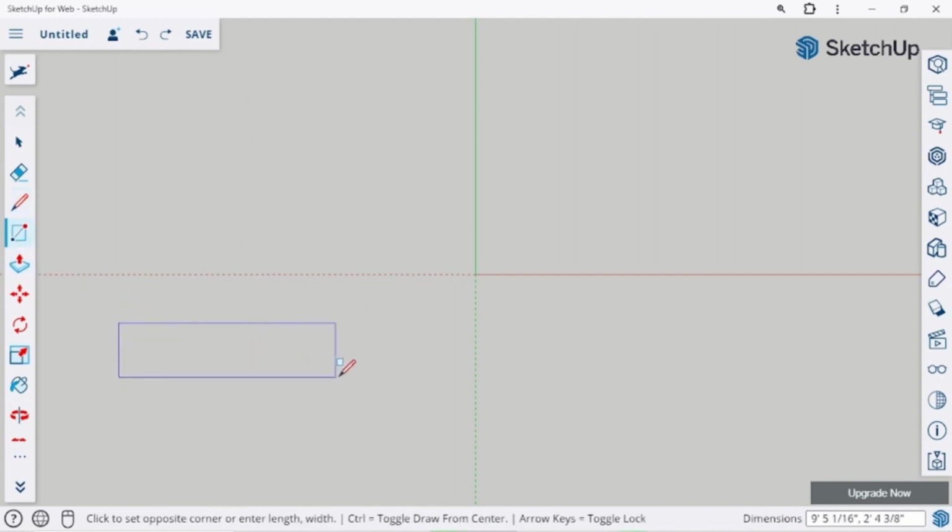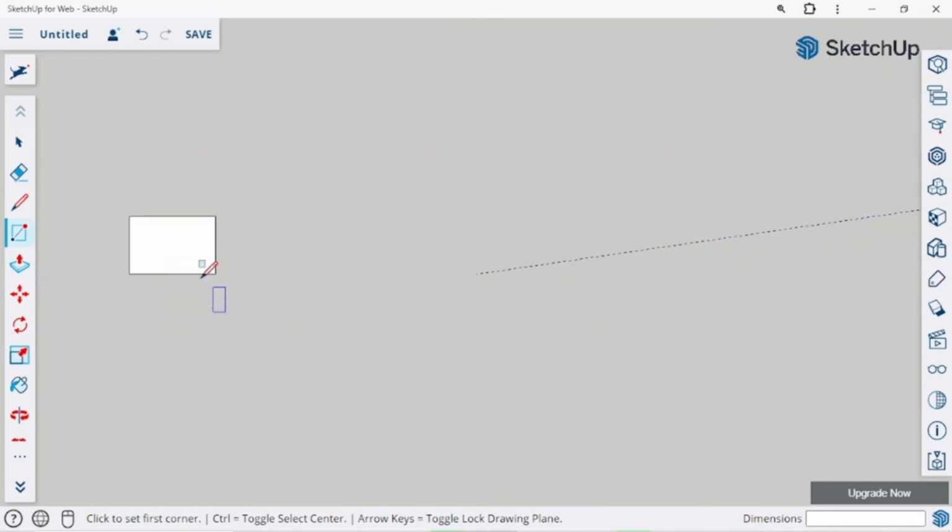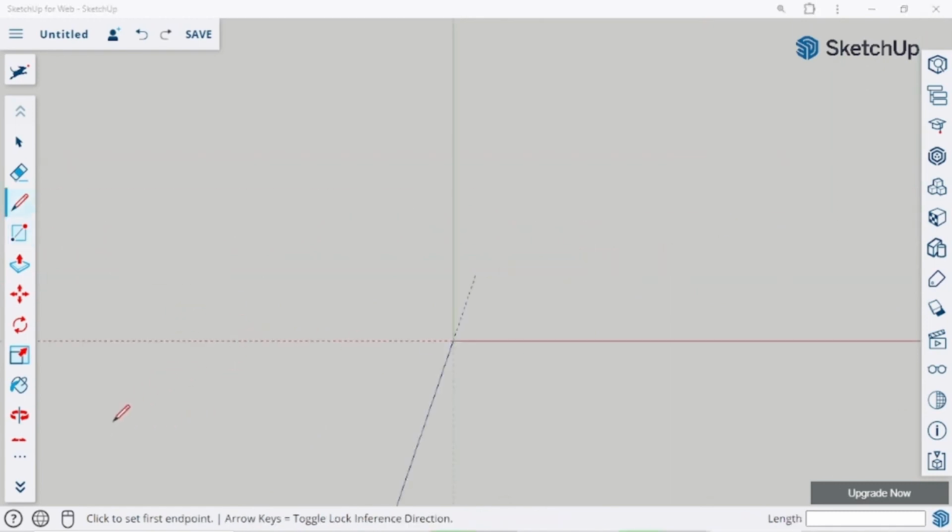So our room size will be, but before we type in our room size, you notice that the more I move my pencil, the more the measurement goes up. One mistake most people do is that once they click on it, they come to click here to type in the measurements. No, you don't do that. You could use it, then type in your measurements. So you may wonder why it didn't show. It did show, but just that it did show in. So we are going to use our pencil tool to draw.